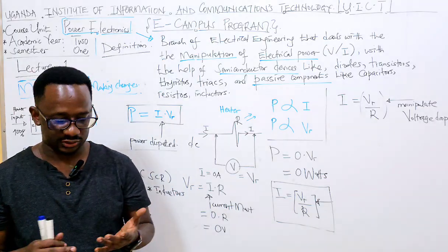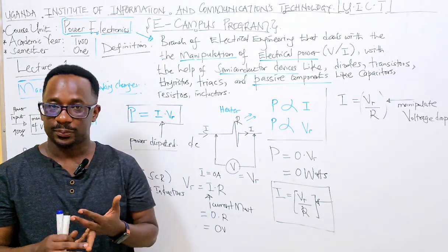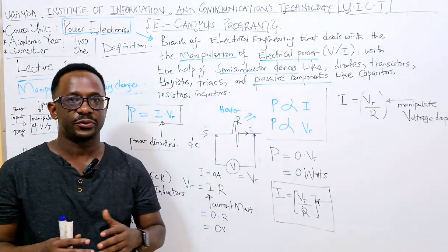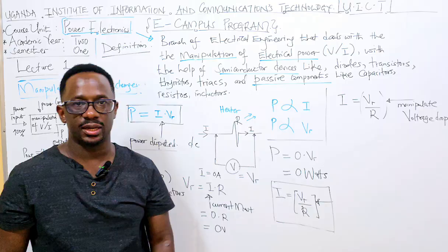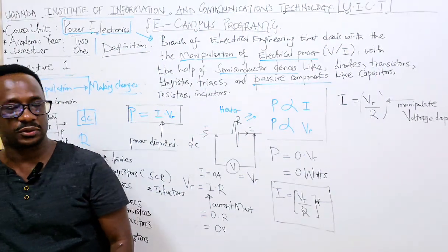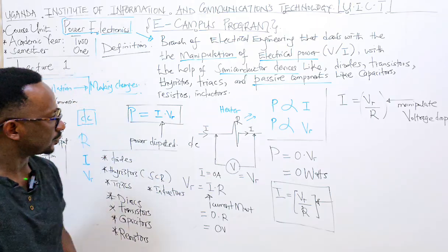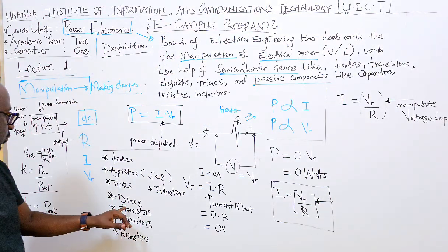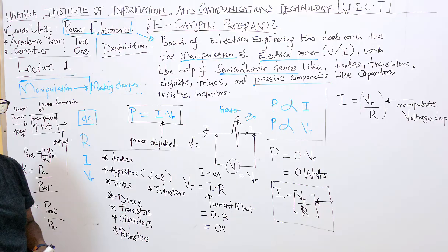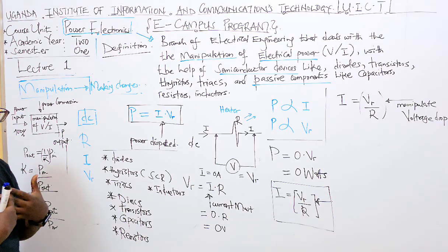They have power losses of their own. Capacitors are not capacitors all the way. It depends on the switching frequency. They could easily behave like an inductor, and an inductor can easily behave like a capacitive load. So we are to look at diodes and thyristors. These components are not ideal.